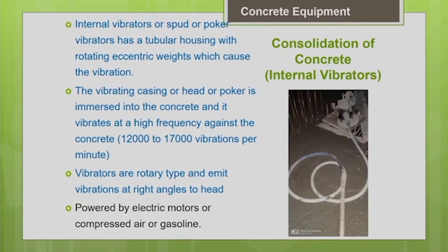So first let us discuss the internal vibrators, which are very commonly used for the consolidation of concrete. We call them needle vibrators, spud vibrators or poker vibrators. There are different names for these internal vibrators. These are more effective forms of vibrators, because this needle vibrator has a casing or head at the bottom. This vibrating casing or head is immersed into the concrete.